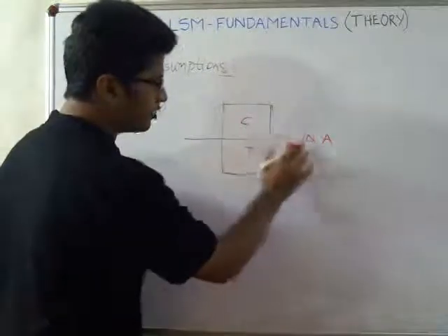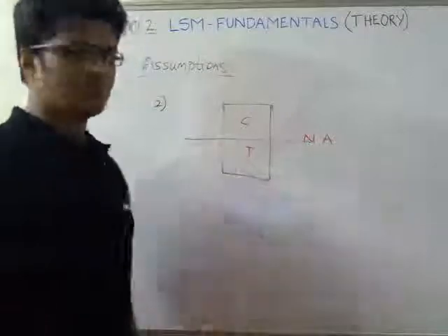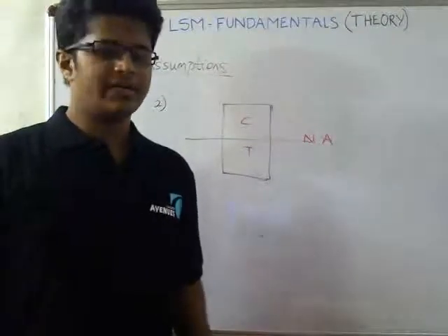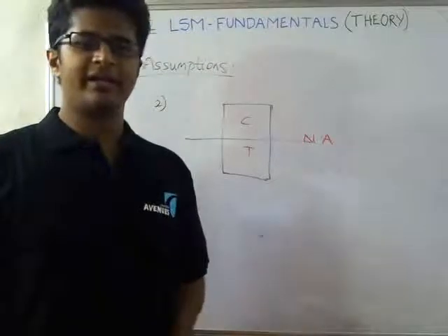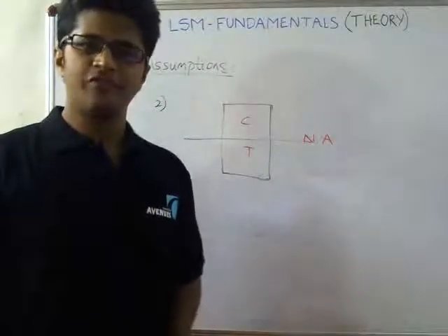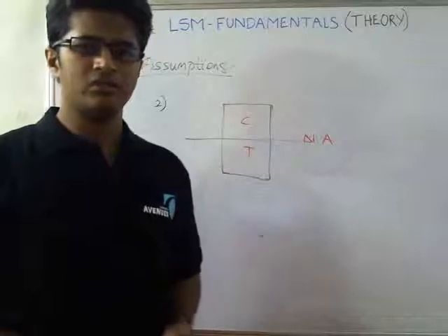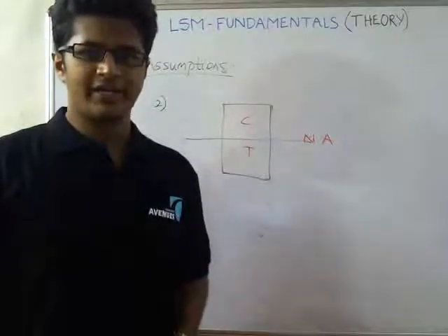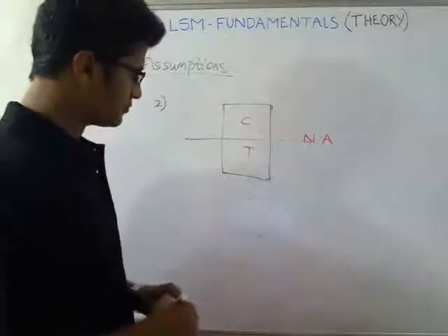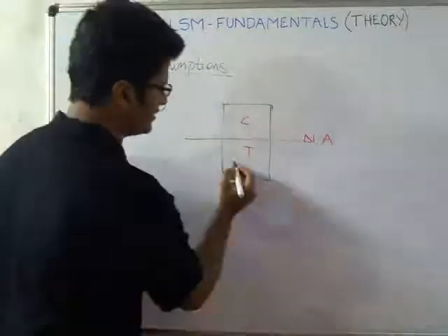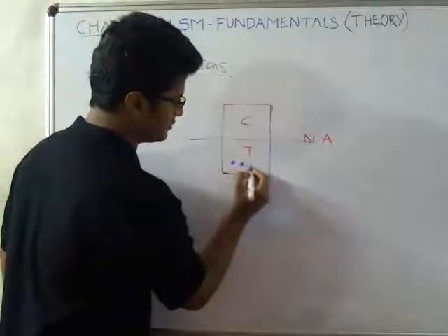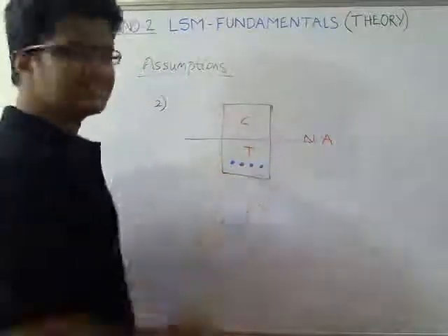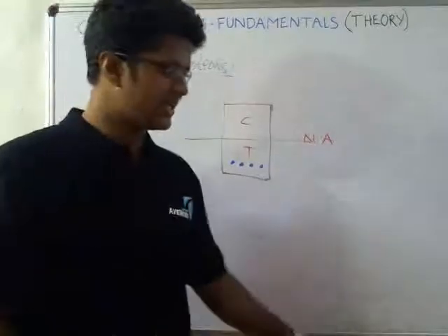The concrete below the neutral axis does not participate in taking care of any sort of tension. The whole and sole part of the beam which is responsible for the tension is steel, which is somewhat like this. So the concrete is neglected. This is the second assumption.